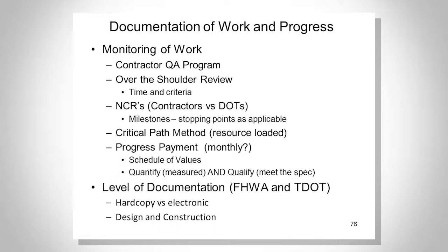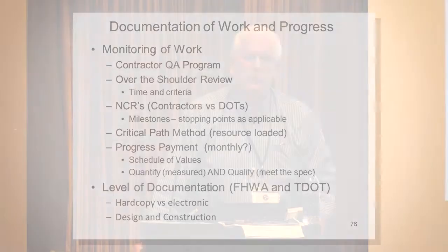Then we get into the critical path method for the schedule. A lot of states with design build, from what I've seen, they ask for a more defined resource loaded schedule, which could be for personnel, could be for usage of DBEs out on the project. As it's a bigger project, and you're putting a lot more ownership on the contractor, but it's still a shared risk. That helps, should give you a little more comfort that as they say they'll work with the DBE the first couple months, 6 months, that they're going to eventually meet their DBE goal.